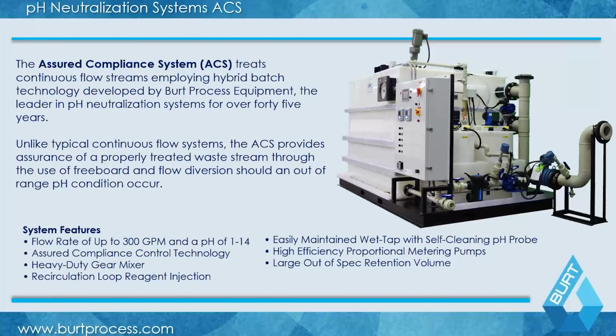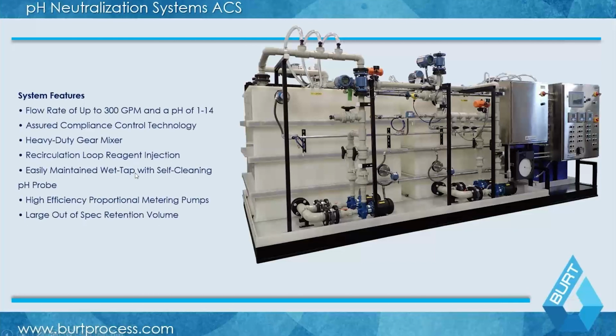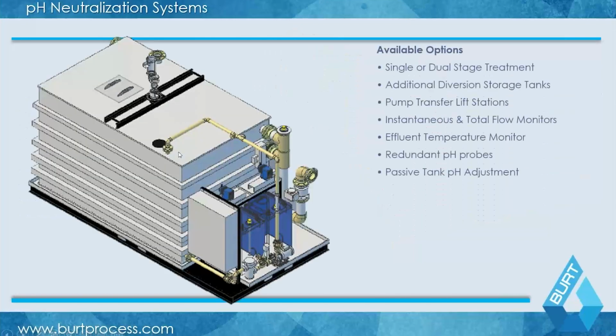A much faster treatment cycle than just having simple drip chemistry, like I showed you earlier, as part of a dual stage design. These can be fitted with different options, such as heat exchangers. They can be multi-stage. You can see here, you can have redundant recirculation pumps, different materials as well. There's a lot of customization that can go into these standard designs as far as instrumentation, PLCs, SCADA integration. But they still at their core have the basic designs that we talk about as part of a standard pH neutralization system.